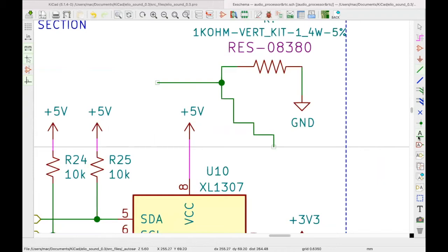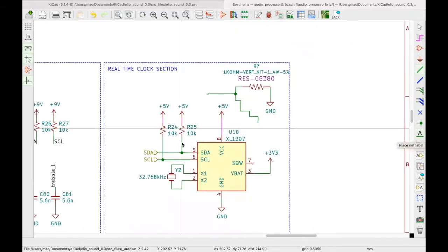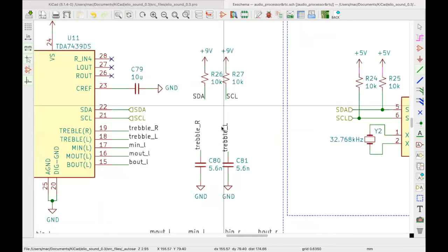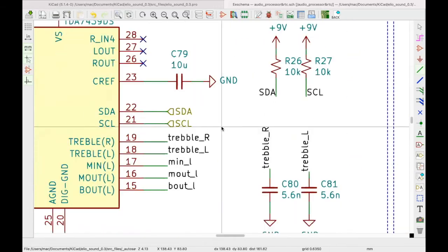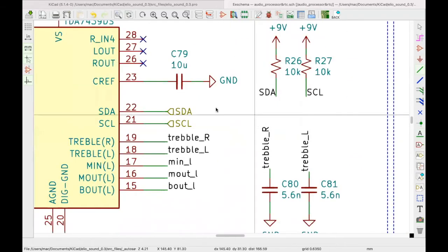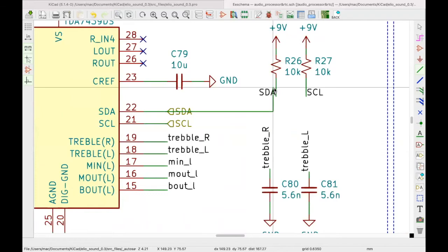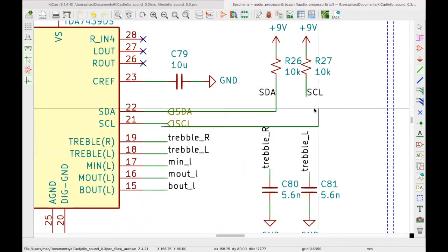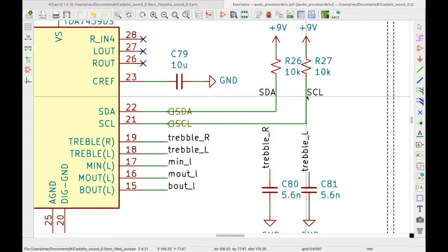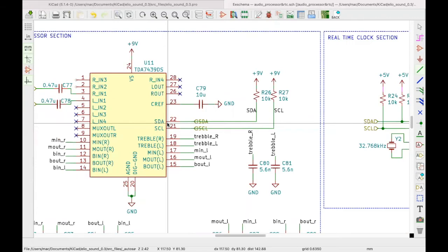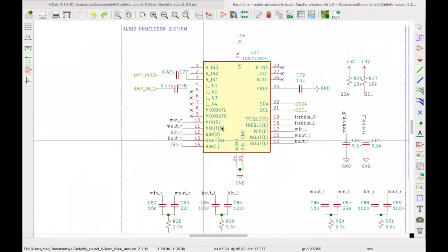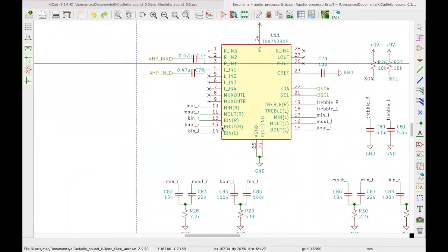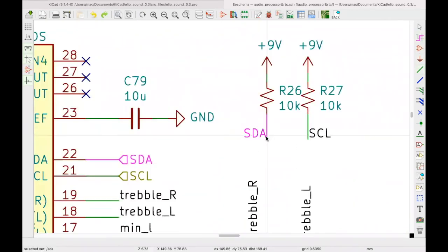This is the net names. We use this to place net labels, and net labels are things like this. You see, here I have SCL, SDA. Say we don't want to draw wires that run all through our design, because it will make our design not so neat. So to avoid all these wires, say that we have parts that are scattered in our design, we use net names. And to check that you've connected this, you just hit on this, and you see they are connected.